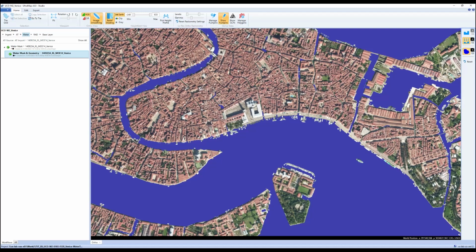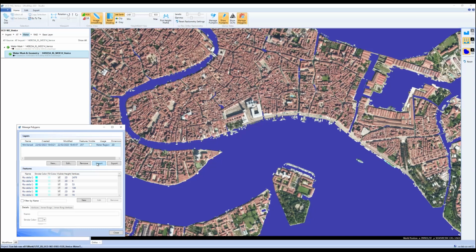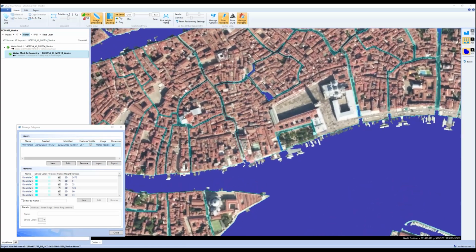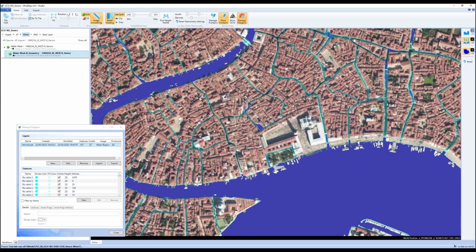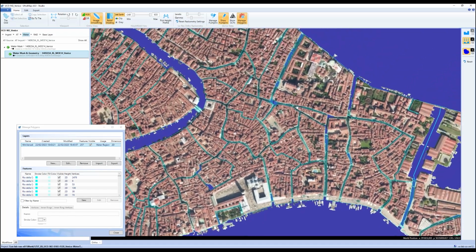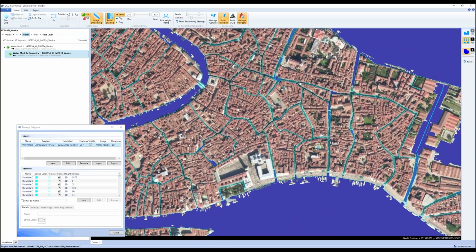So to be able to handle such a project area in an efficient way, we offer an option to import data. So to import an external water mask, and we did that for this region here. And here we see the display of that vector data. So for this example, the data comes from OpenStreetMap. The import supports either 2D polygons, so just to replace the classification data, or it can read 3D polygons to also replace the water geometry.